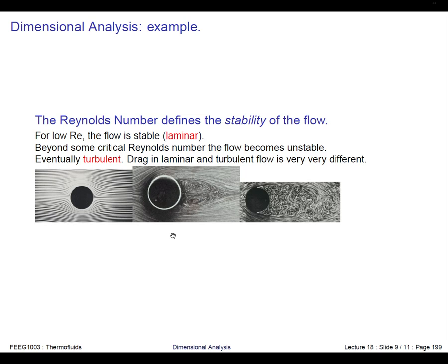But I just want you to think about the Reynolds number, and we could also do this by changing the viscosity. Let's say we keep the velocity the same, the length scale the same, and the density of the fluid the same, but we reduce the viscosity. This is like going from treacle to water to air. With the same thing and the same velocity, you'd still get the same change in the flow around the object. You still get the same flow patterns.